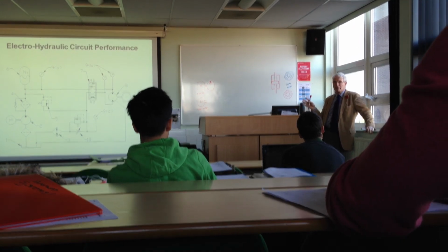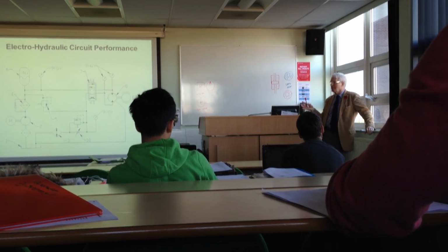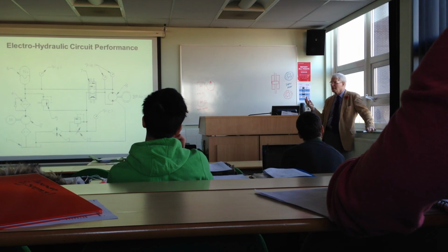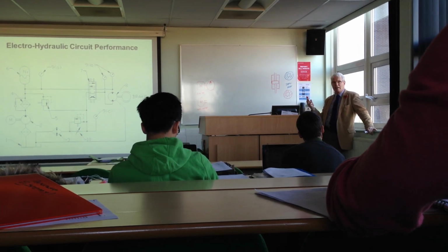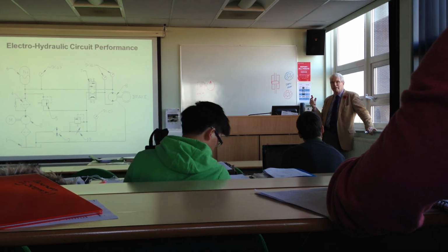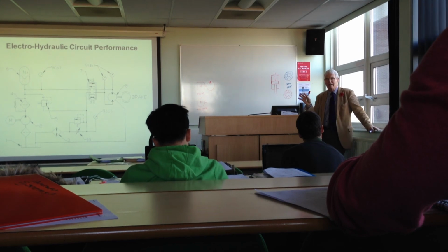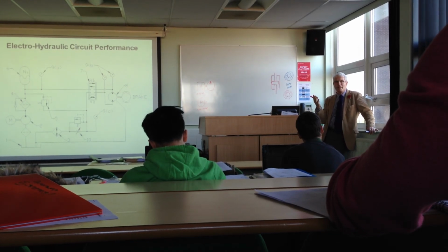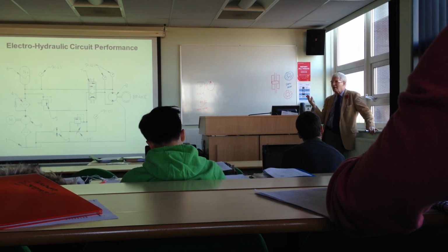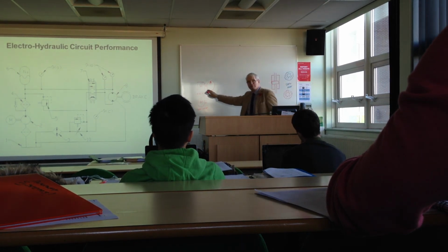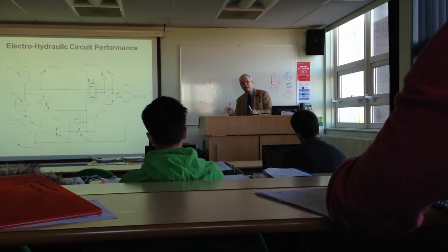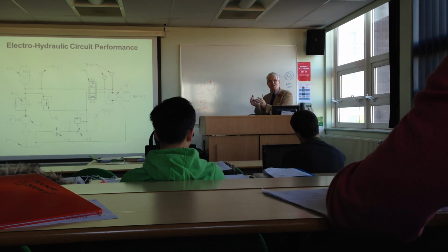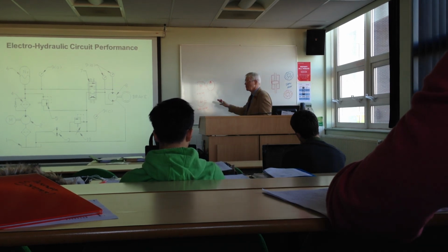On the A380, because it's the most recent aircraft to be flying, things are improving. A, they push the pressures up, so they're working at 5,000 psi, 350 bar. But electric motors are now getting much, much smaller. And they've also got such big wings that they would like to distribute circuits around the aircraft. So actually on the ailerons, they've got three completely different control systems. They've got a traditional fly-by-wire, where they've got power coming off one of the engines. They've actually got little power packs that are part of the actuator. So out on the wing, they've got a complete circuit. Okay? So I think we will assume a complete circuit.